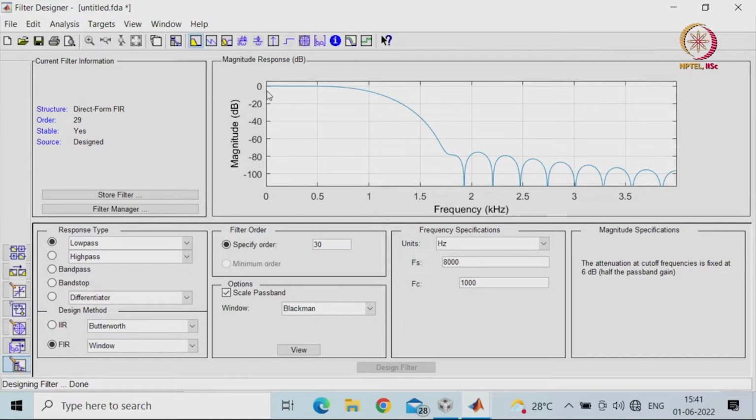0.707 of the magnitude. You have to be careful when designing your filter, as the output amplitude may be modified; you will get a scaled version. If you want 0 dB, the frequencies I can pass, as you can see, are only up to 500 hertz. If you are doing anything beyond it, you will have attenuation in the magnitude, so you may have to compensate.